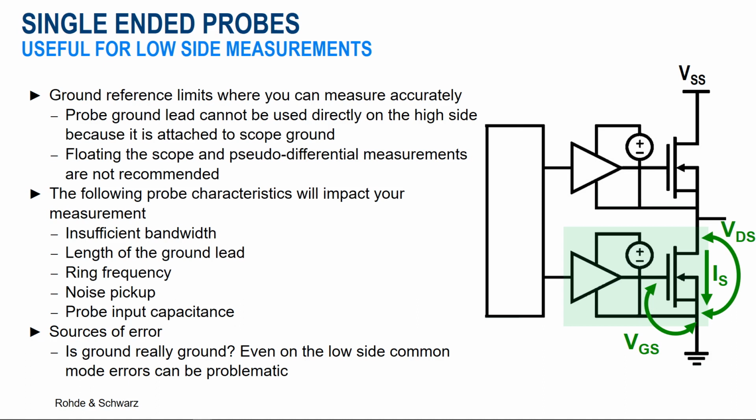A passive probe is convenient because it ships with a long ground lead, usually around 6 inches, which allows connecting to a single ground connection and probing a wide range of test points. While convenient, it's critical to understand a probe's rise time versus bandwidth, input capacitance, and ground lead inductance. Because you're connecting to ground, it's important to be aware of ground loops and learning to avoid them.